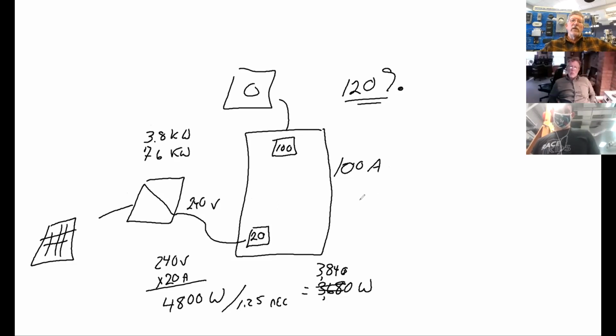And that would be a situation where you have a 200 amp box and 200 amp service coming from the utility. So these are just normal configurations here, which then dictate the size of the inverter that you could hook up and not exceed. So if you had 200 amp service with a 7.6 kW, then you'd have a 40 amp breaker coming in, and you'd still be within the 120% rule.